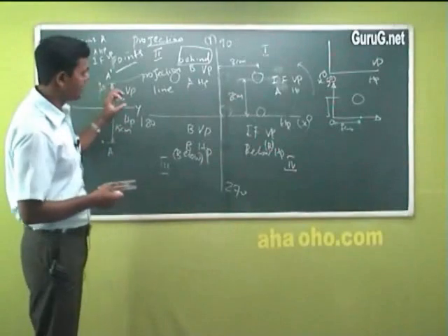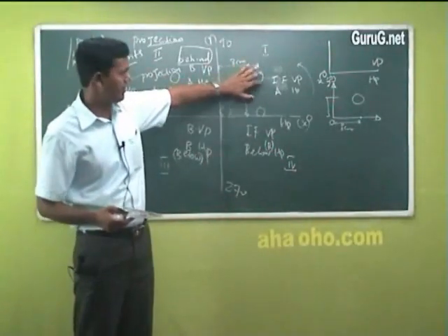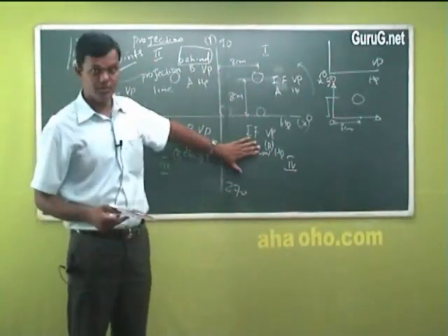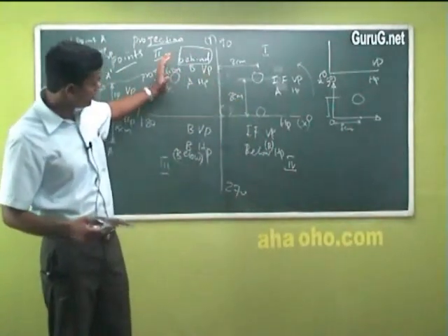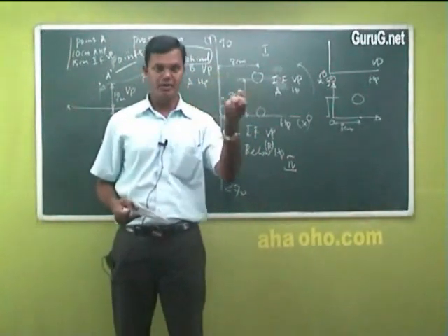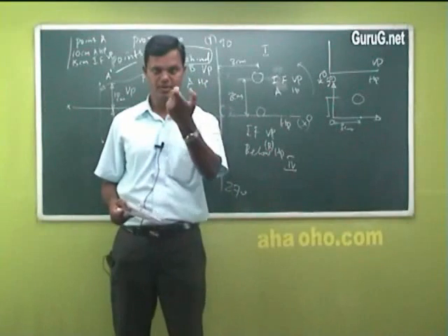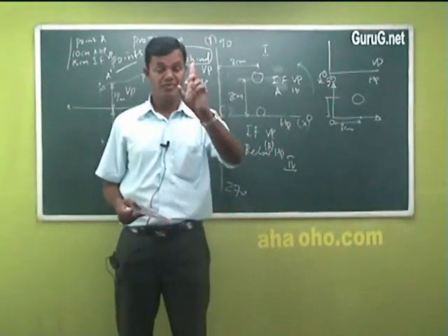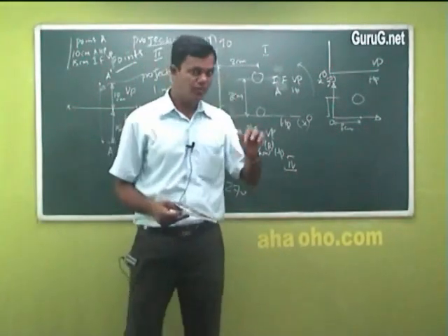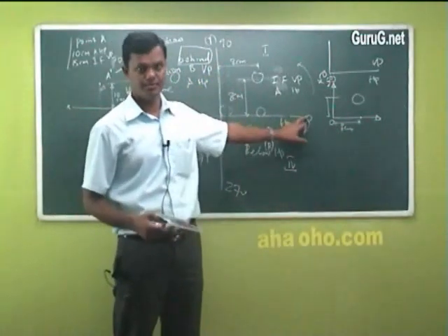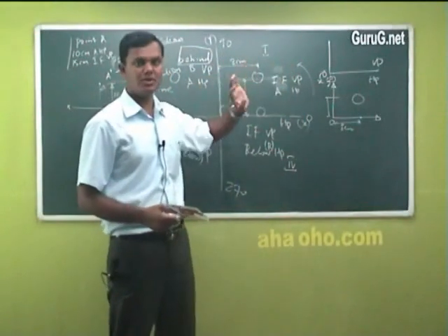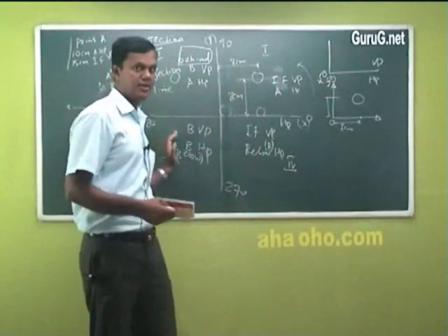So that way it is front and top view. This is about placing an object or a point in quadrant number 1. Like this, we have to see quadrant number 2, 3 and 4. This is only for points. Before going to 2, 3 and 4, I would like to say that in the engineering drawing syllabus of first year, that is your syllabus, we are studying only first angle projection. Everything is placed in the first quadrant, in different manners. We are not reading about the second, third and fourth.